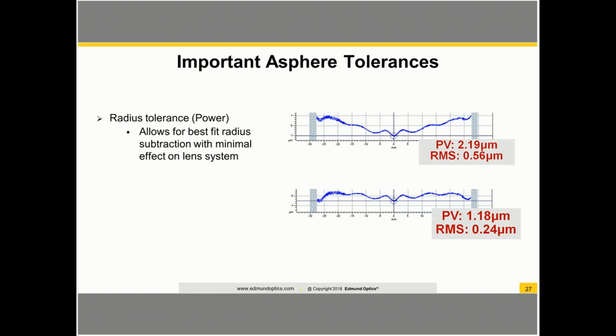I'd like to add a couple comments here. One of which is we would like to discourage our potential customers from overspecifying Aspheric lenses. They are not the cheapest to manufacture, so overspecification leads to a longer than needed and harder than needed manufacturing process that results in higher costs and higher prices. Another aspect is please consider moving some of the tolerancing off of the Asphere component and redistributing it on the system level, either into other components in the system or via some type of alignment compensation.